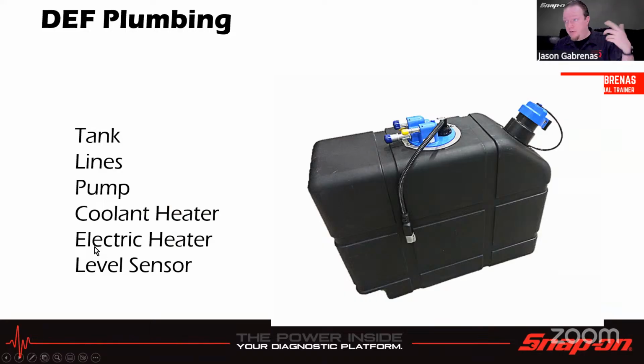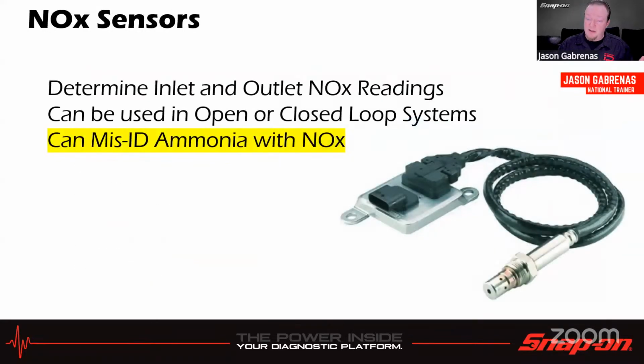Now, how do I fill it up? You've probably seen the big jugs of it at the store. I mean, they even have it at like Home Depot and stuff. Depending on where you live, they might even have it at the pump. I know the gas station down the street has it at the pump, and you just pump the DEF in. So a lot of diesel trucks go by there. So you got a diesel pump and you got a DEF pump right near each other.